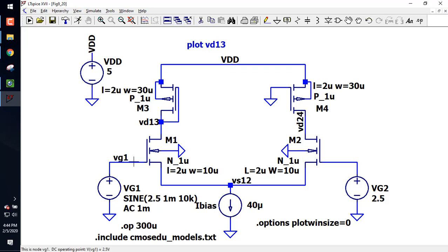Now, this is a really subtle question. If you get this on an interview, you'll impress people. Why do they have slightly different currents? The body effect's exactly the same in each of those transistors. The sources are tied together and the bodies are tied together. It has to do with the VDSs, the drain to source voltages.